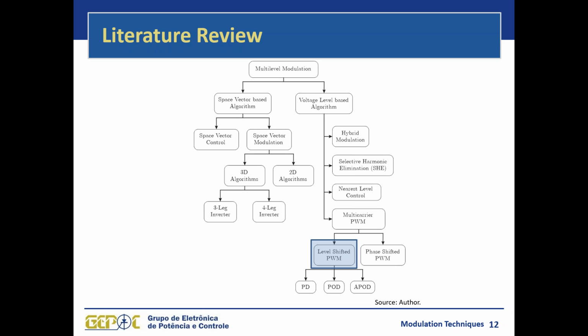Another approach that is becoming more popular in recent years for multi-level converters is model predictive control, which can also be applied with very nice results for multi-level converters. But in this work, we are going to focus on the level shifted PWM, especially the phase disposition PWM.